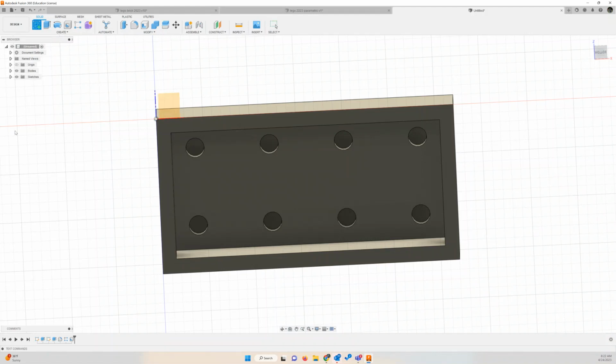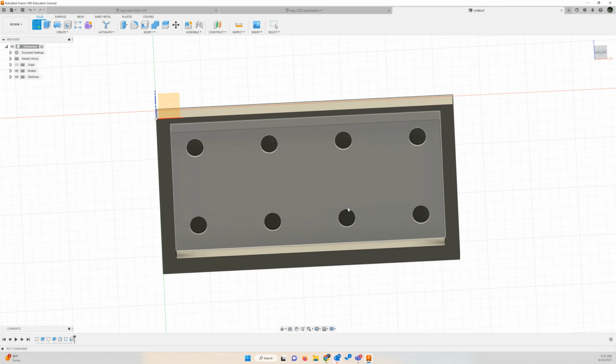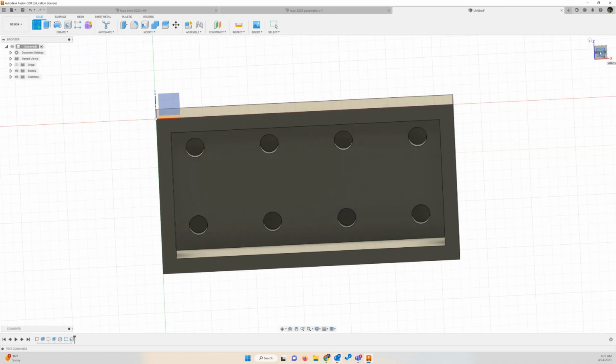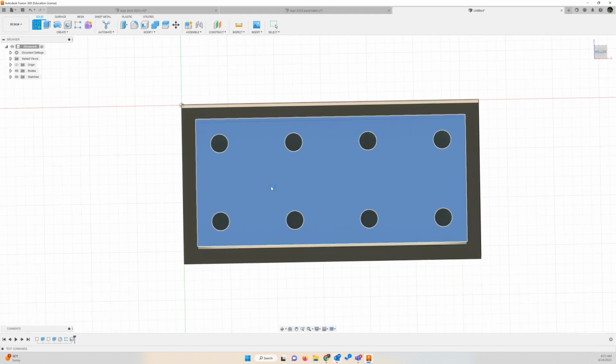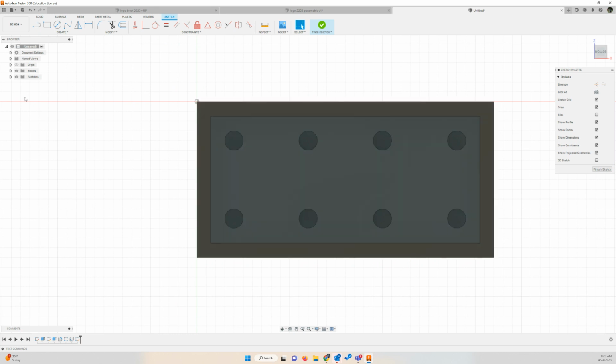Let's create a sketch on this bottom face. So I'm looking at the bottom of, as I roll my mouse up here, the bottom of my design, my brick. Select that bottom face. Now, the bottom connector is centered between 4 top connectors. So I see 4 top connectors here, but those aren't my 5 millimeter diameter circles. So I'm going to turn on construction.